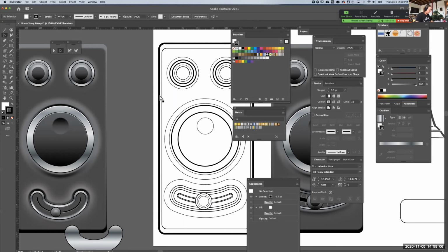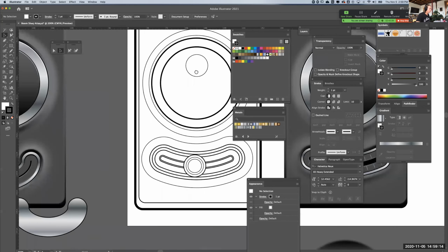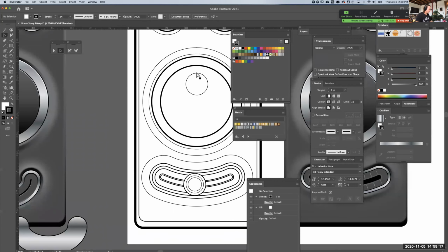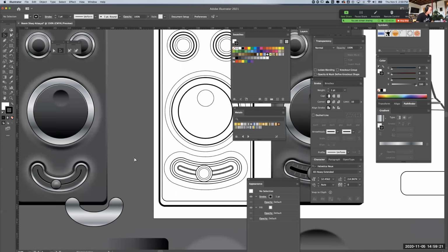So now we're getting some nice line weights. Get rid of some of this stuff. I got to double up on that because you don't want those reflection stuff on there. There. This is a material change. This one right in here is a material change. So this one is going to be 2, and this one is going to be 2.